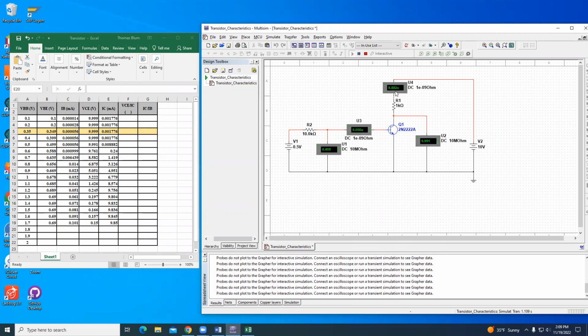The main thing I want to point out is that the current is in microamps, and I wanted it in milliamps. So I owe 3 zeros in here. The meter's reading 0.056 microamps, but I put it in over here, and the same thing over here for the 8. I owed 3 decimal places to convert from micro to milli, so 0.008882. So I can carry on getting those statistics.